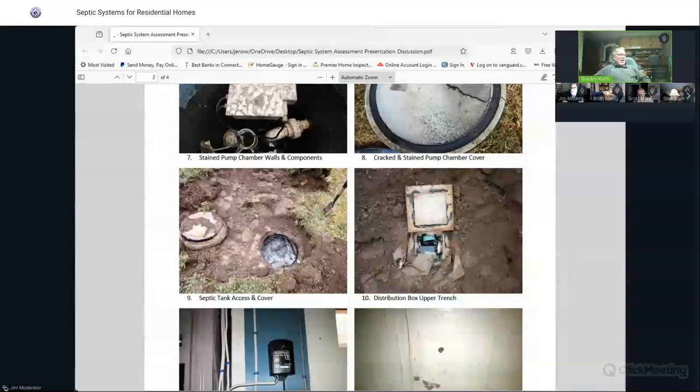Because once stuff like that goes out to your leaching field, depending on what it is, that's when you can cause failure in your system. So there's a good purpose for having them in there. To take them out, you take the cover off, which may not always be so easy if the cover's down a few feet. People have probably seen some septic tanks that are right near the surface, but they could be down 3-4 feet too. I've seen ones that deep. So it may not be easy to remove the cover, but you remove it and you just wash off the filter.